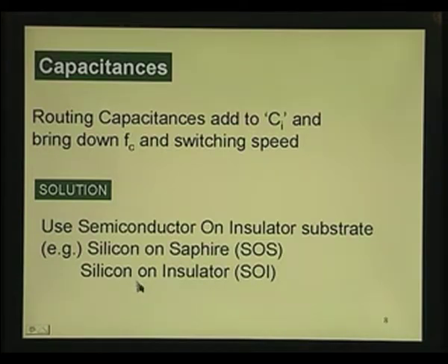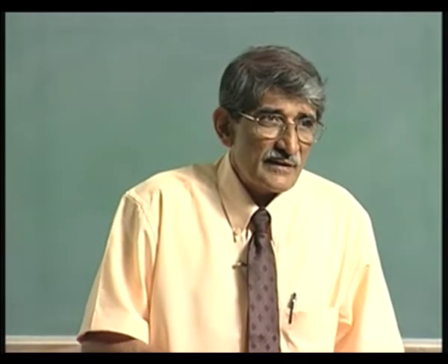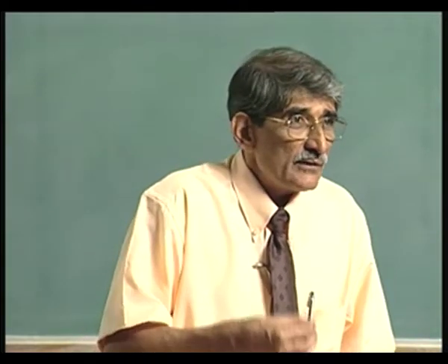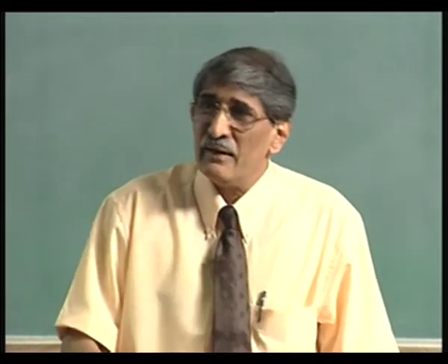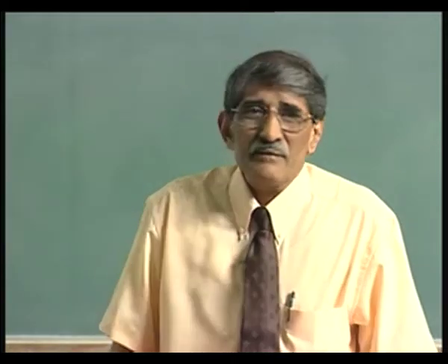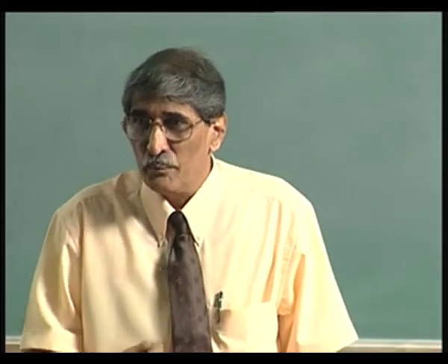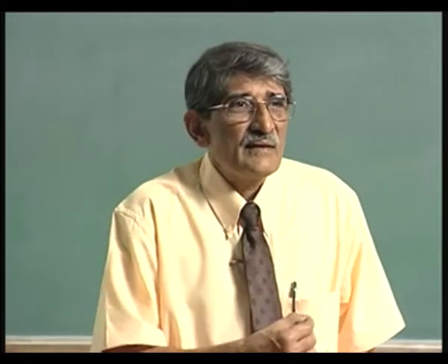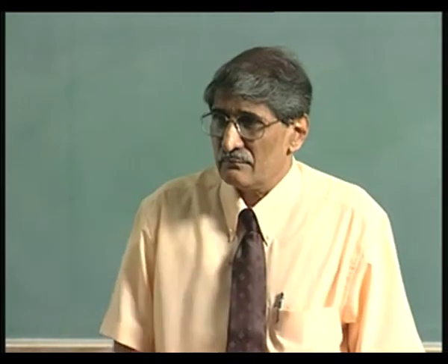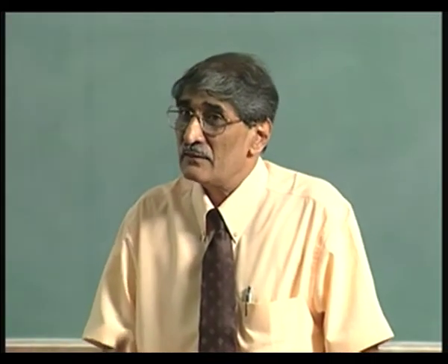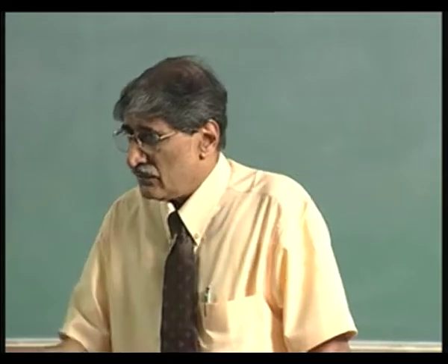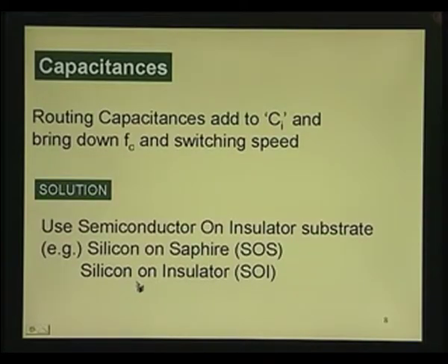Materials like gallium arsenide themselves can be very high resistivity materials. You call it semi insulating material. Instead of insulating material, semi insulating. Insulator will have resistivity of about 10 to the power 13, 10 to the power 14 ohm centimeter. Semi insulating material will have about 10 to the power 10, 10 to the power 9, which is much higher compared to a semiconductor. So, those concepts, in fact, I am just giving you only a flavor today. More about this we will have occasion to discuss.